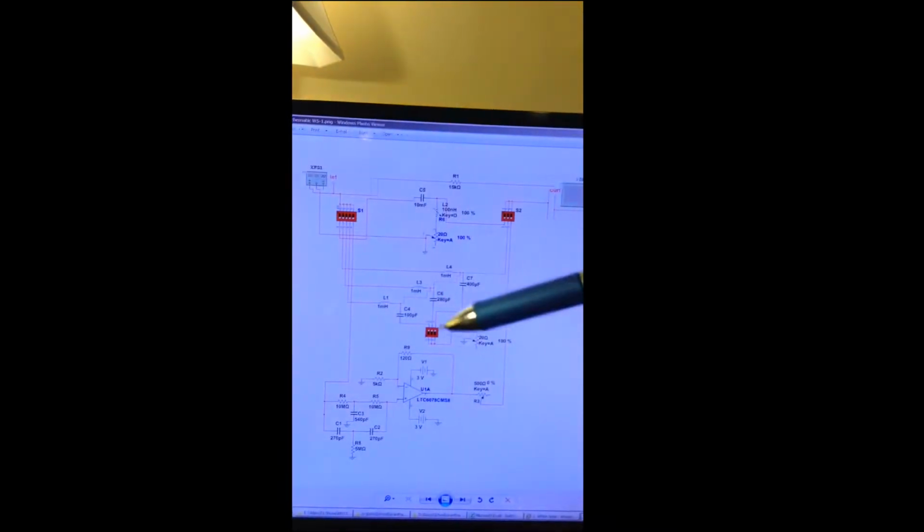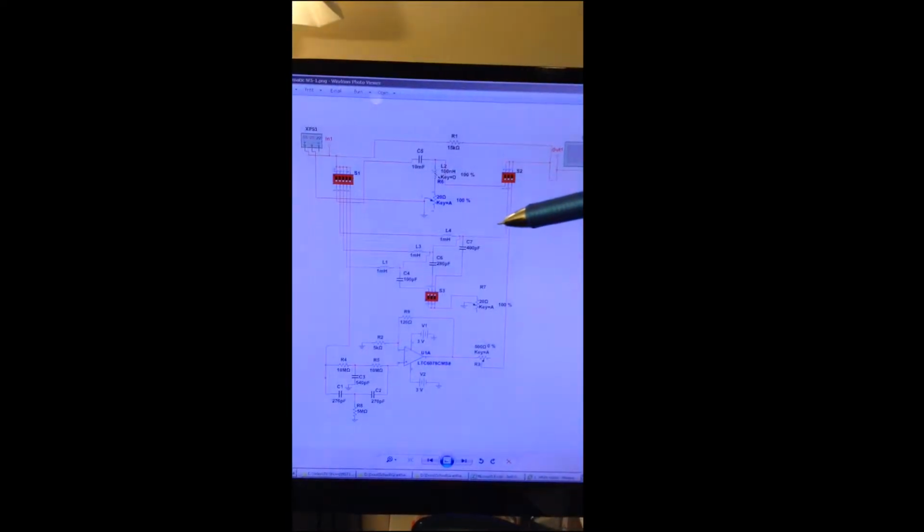You'll see that we have 3 dip switches here which control the selection of the stage or branch of these arms, and it was not enough to connect and disconnect the input signal to the 3 branches, because if the outputs were all left connected to the output signal, then they would leach off the signal, and that wouldn't be good enough. So we have to change and isolate both the input and the output to the stages we want, and isolating the stages we don't want so that they don't leach off our signal.